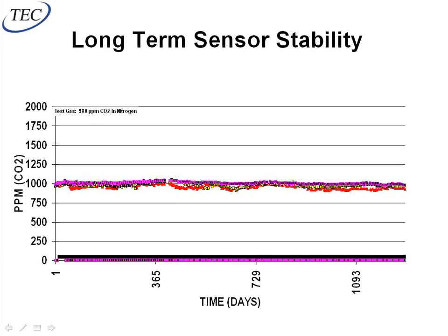And then I can still go higher to that for temperature reasons. So I'm not going to bring in more air than I would have on a normal job. I'm going to bring in less when nobody's there. When everybody's there, I bring in the normal design amount of airflow. If that normal design amount of airflow would have caused me to overcool the space, then yes, I'll have an overcooling issue, and I can either kick on the reheat, or I can just leave it be as is, depending on what I would have done on my normal job. The point is I'm not going to modulate it more than a regular job. I'm going to modulate up to a regular non-DCV job. And the same thing is true on the air handler on the outside air damper.